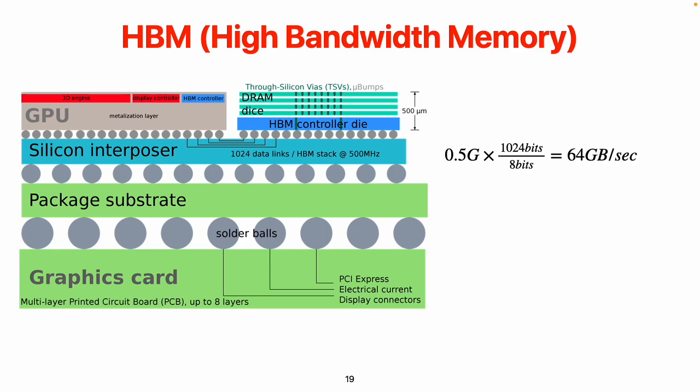A lot of people might think that 3D die stacking is going to help us with the discontinuation of Dennard scaling. Dennard scaling says that the more advanced the technology, the per-transistor power consumption is not going down. And the per-transistor power consumption is related to the temperature, the heat that's generated per transistor.